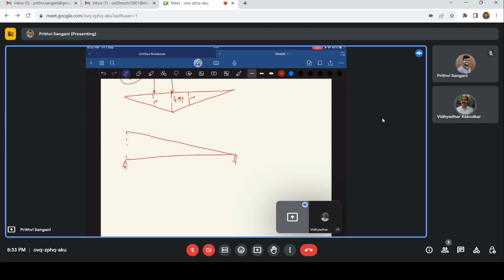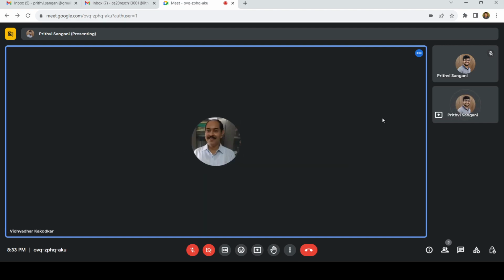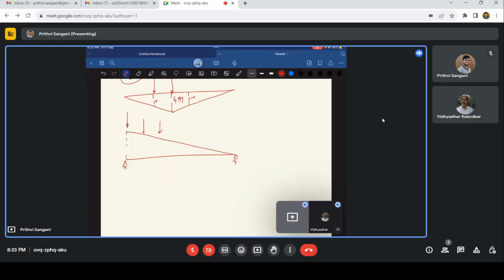Anyways, for the shear force, you need to just lift this up. Again, if in the question they are asking that the loads can be reversed, or it is not only going from left to right but it can also go from right to left or something like that, then you need to place the maximum here, and then smaller, and you do iterations. So one or two iterations, case one, case two, you can directly find out the maximum shear force.